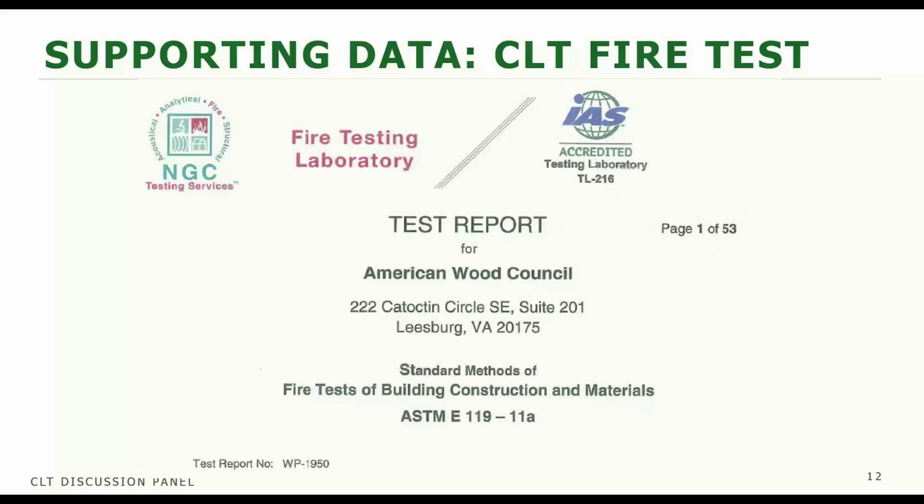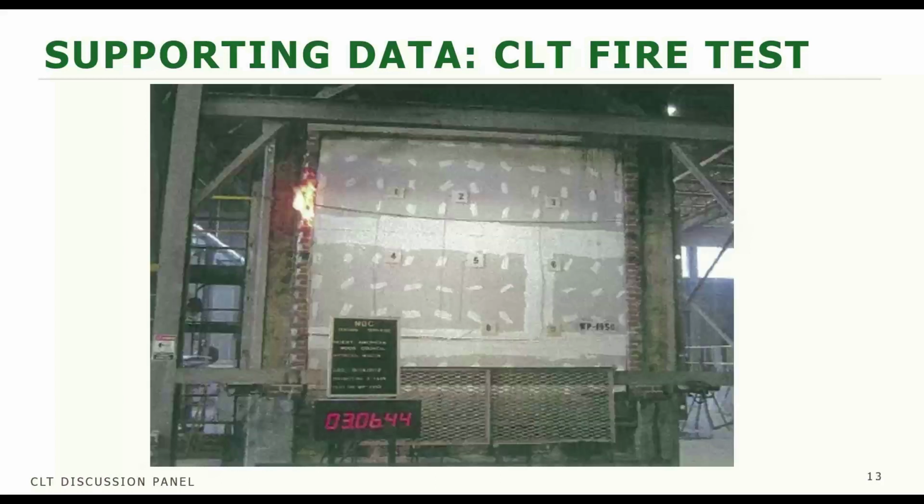Some of the supporting test data that we have, you can see here, is one of our first tests that we actually did on CLT. This was an ASTM E119 fire test that was done back, I believe, in 2012, perhaps 2013. I don't remember the exact year, but the year the test was done isn't so important as the results of the test. This was a 5-ply CLT panel that had a layer of 5/8 inch Type X gypsum on each side. The wall was loaded to approximately 87,000 pounds, which was the maximum capacity of the machine they had at this particular test facility. So, about 87 kips, that's a pretty substantial load.